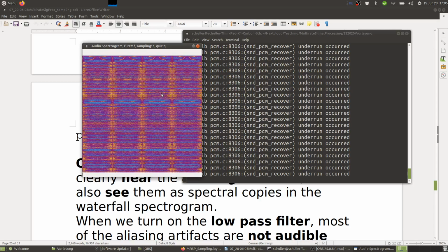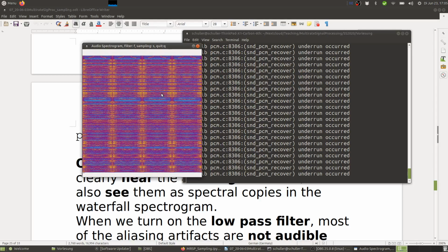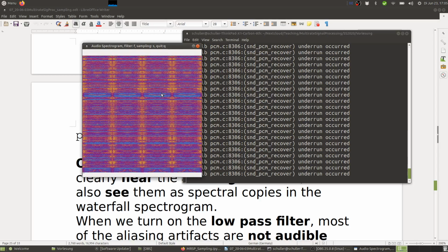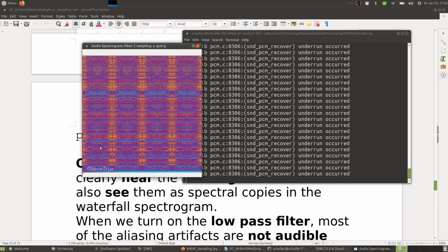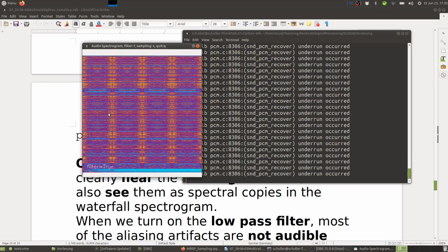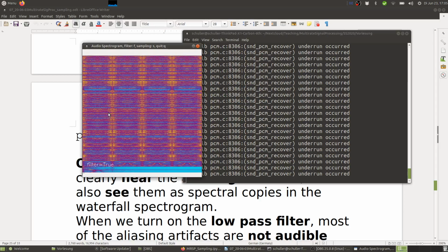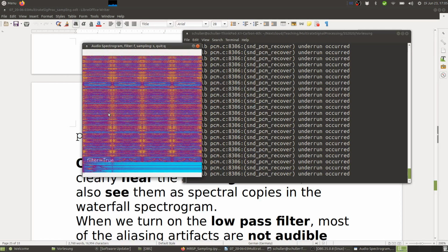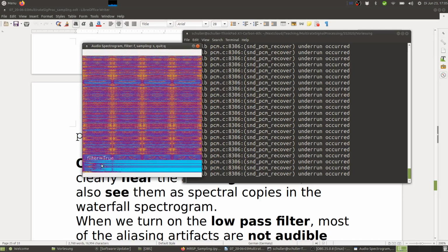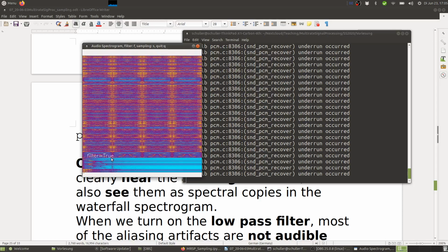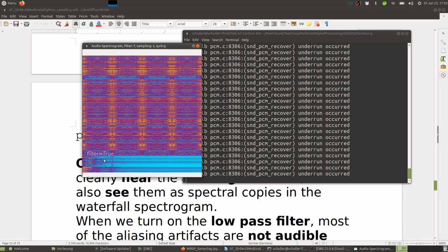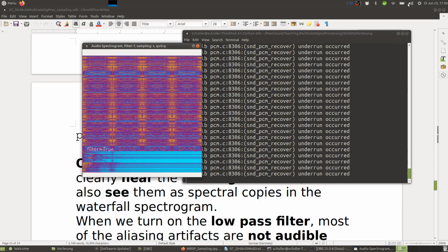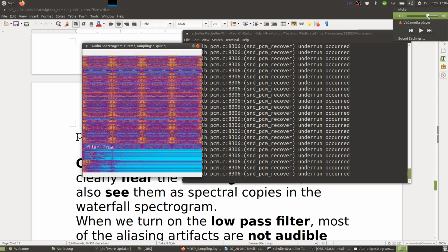So now let me do it again with whistling, and now using the key F for toggling on the low pass filter. And now F, filter is on. Now it was hard to hear because much of the energy is lost because of downsampling and filtering, which you can also see because there's more blue here. But I could actually increase the volume here to hear it more easily.